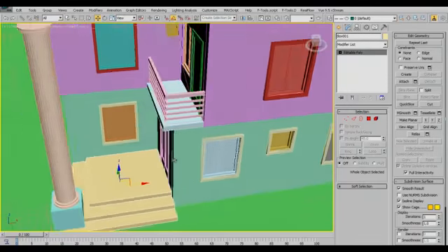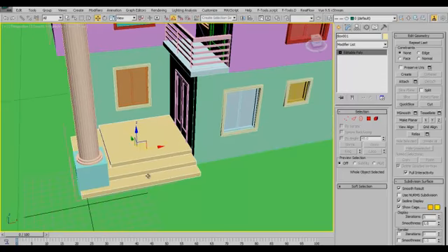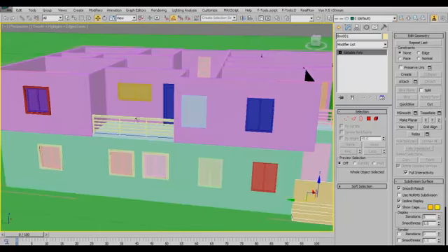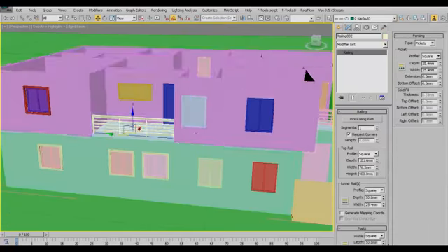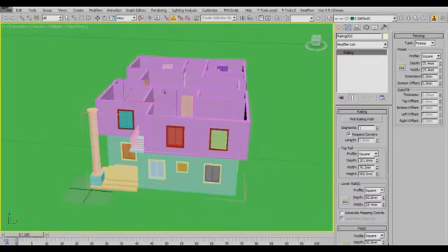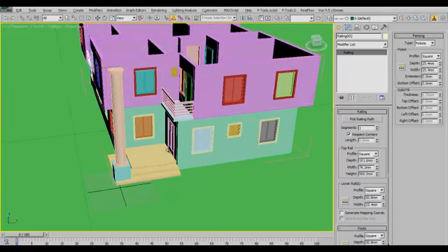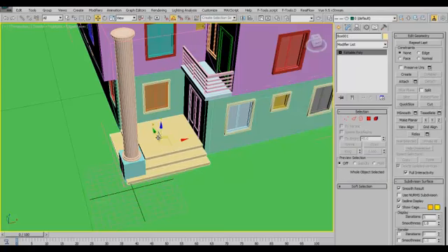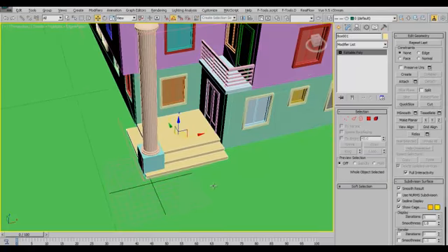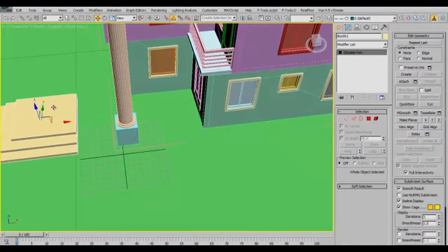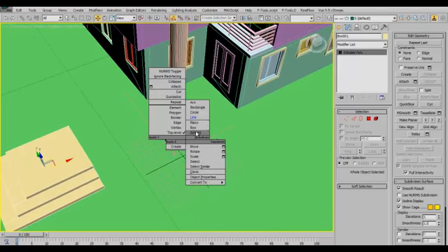which is a 450 step up, which is 150 per step, and I've included this railing equally, so we have the balcony. So what we're now going to do is create the roof. Before I do that, I'll just show you how to create these stairs.